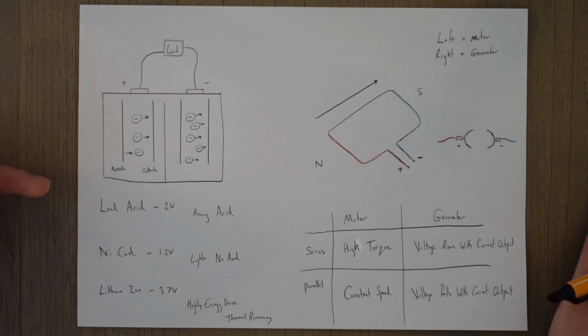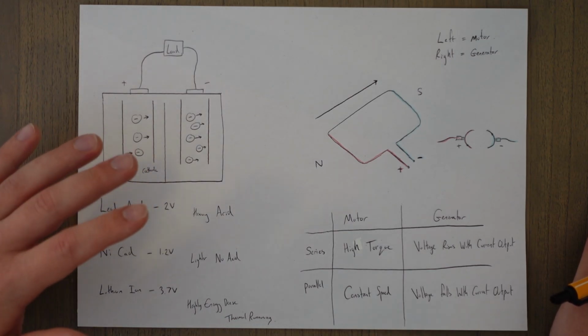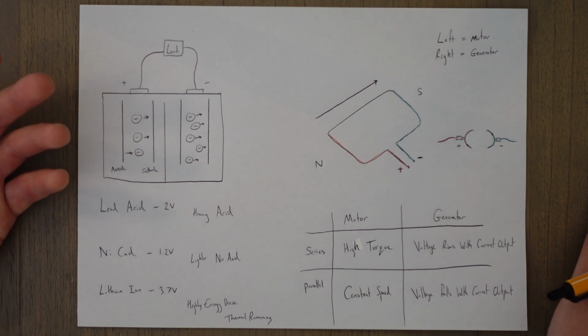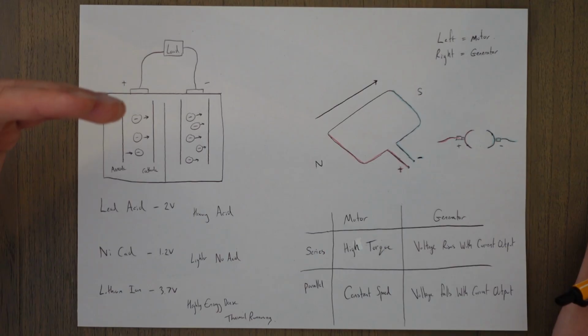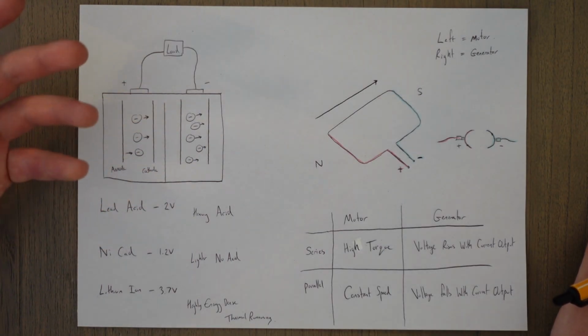In aviation, there's three main types of batteries. All are secondary cell batteries. Secondary cell meaning they can be recharged, whereas primary means they can't be recharged. And to recharge, you normally add a voltage back to the battery about 10% higher than the battery is rated for.